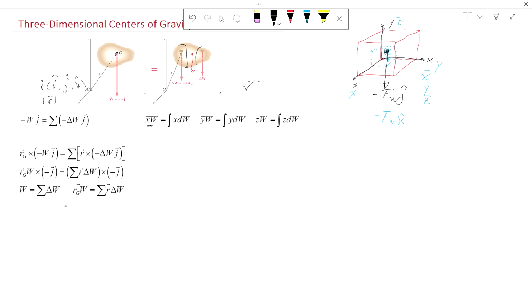In that case, it's simpler to find the centroid of the whole body, and then find a single vector r that will take you there, so that we can find our main force. Remember how before we had an example where even though we were computing the area, that region was really a force? Same here, the volume will represent the amount of force of the body.